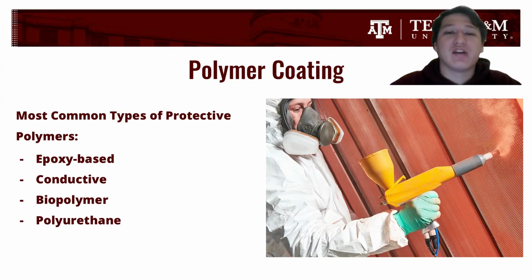For example, epoxy coatings are frequently applied to pipelines and storage tanks to prevent rust and degradation inside of them, while polyurethane coatings are used on steel structures and equipment exposed to the extreme conditions of being outdoors in the humid weather, providing much longer lasting protection.